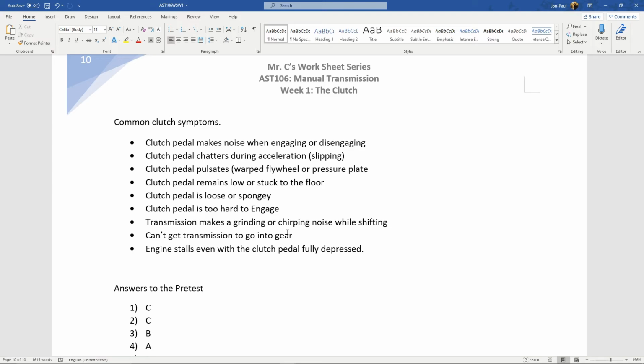So I've done that. Now I can get to the clutch. I have no reason to go in this transmission. So my labor time is going to be vastly different if I do have to go into the transmission, because it really is the two or three or four gears that create whatever gear ratio you're having a problem with. That's going to require the entire transmission A, removed from the vehicle, all that labor, and then B, disassembled, much, much more labor. So this is super important we nail this down.